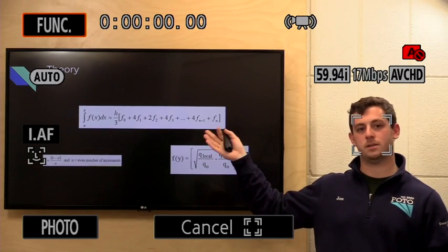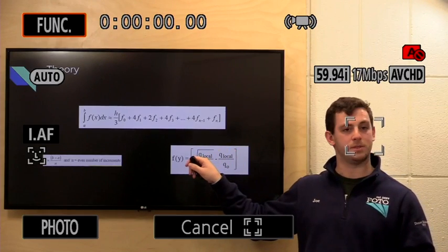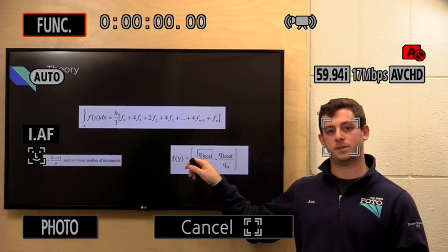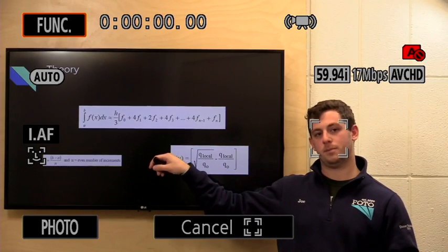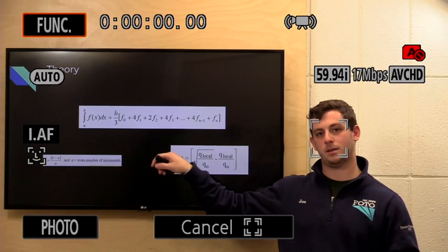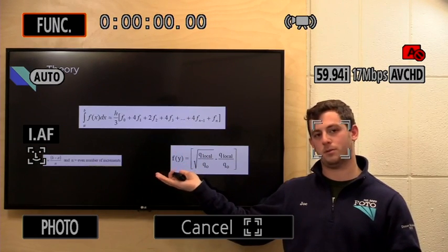And we use this step H, which, as you can see here, for Simpson's rule, we need to have an even number of steps, and we integrate from the beginning to end of the chord, where we look at the number of steps necessary, which gives us our step over the chord H.